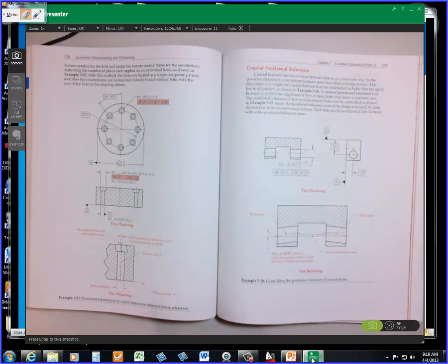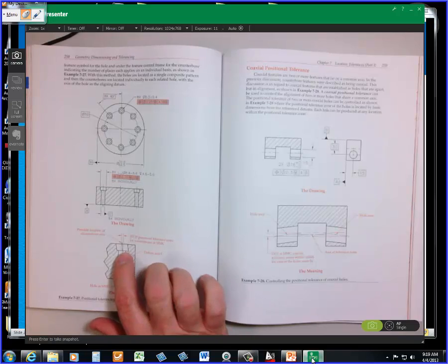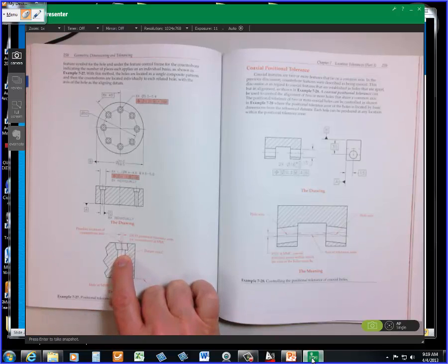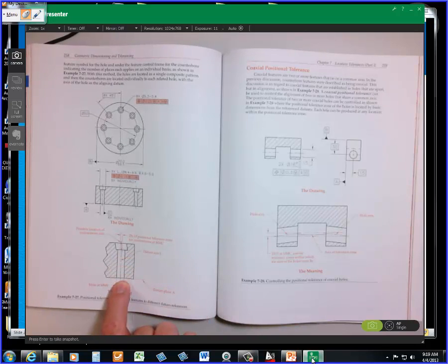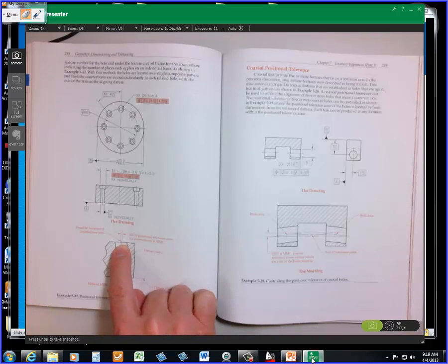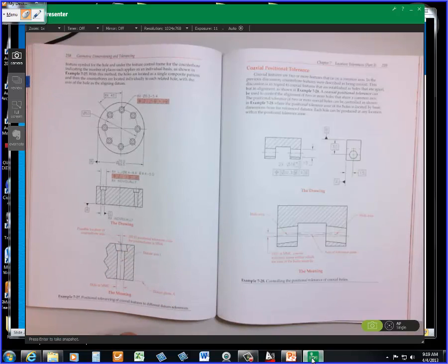So when that is true, then it can be out of position like so. Looks pretty wacky, doesn't it? On page 258, where you've got the diameter, the long pilot hole, but then the control of the counterbore is allowed to fluctuate on its own and considered individually.